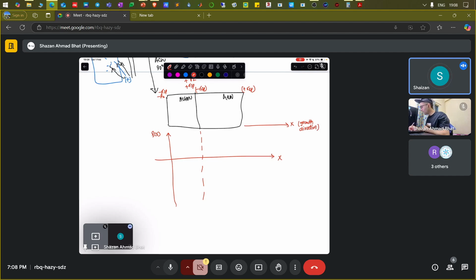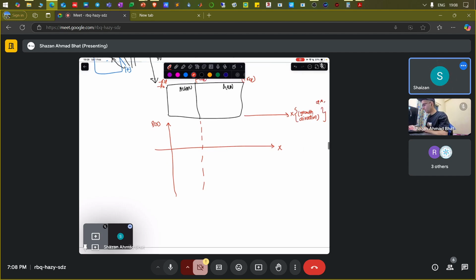So layer by layer means if you take GaN, then you grow it layer by layer, the AlGaN, and it forms the aluminum gallium nitride. That is how the growth is basically done, atomic layer using something called molecular beam epitaxy or MOCVD, metal organic chemical vapor deposition. But that's not of your concern. You just have to understand the concept.